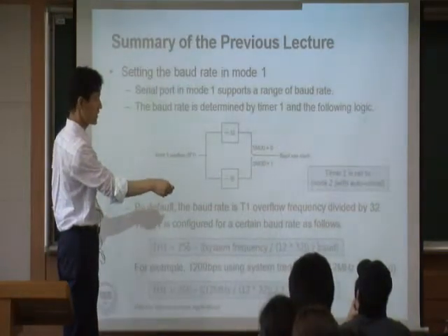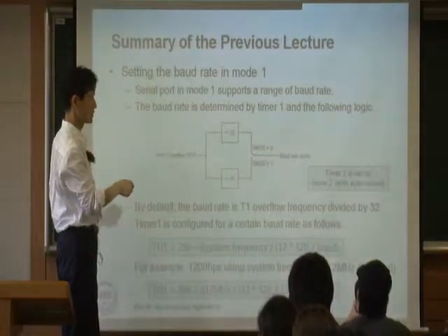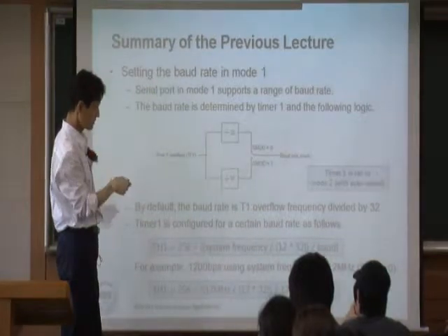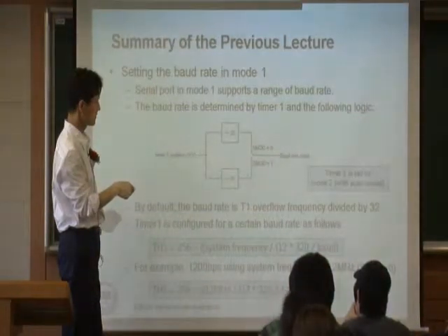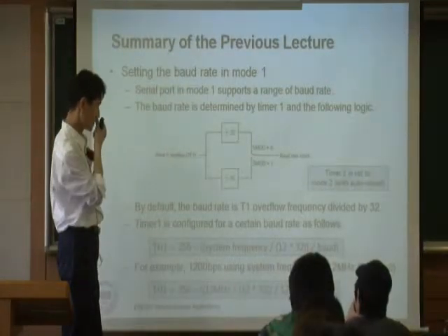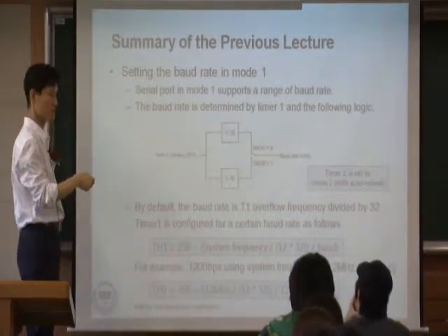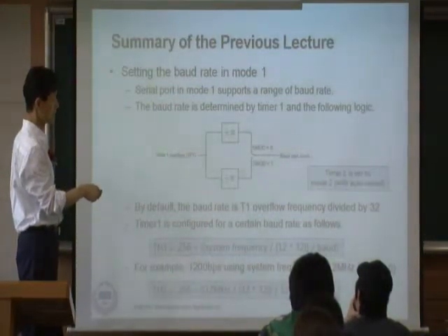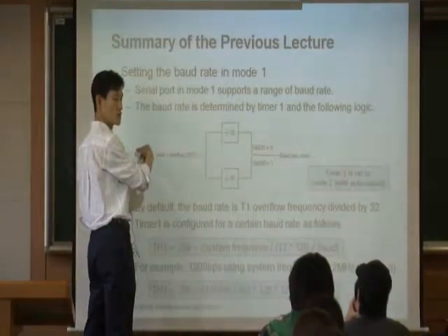But this clock, eventually, we want to have 800 microsecond. So therefore, right here, we want to have how much? 800 divided by 32. It's almost 3 microsecond. So that's the delay that you want to have in this timer.